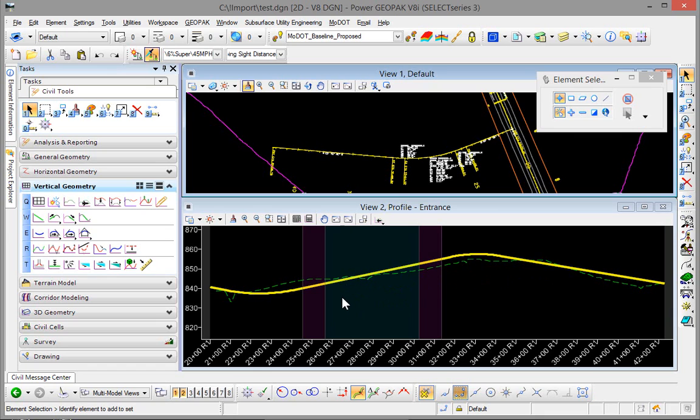You can also come in here and design special ditch profiles along your baseline and target those with in conditions through the use of point controls. So that's how we deal with using our design standards and establishing our existing and our proposed ground profiles.